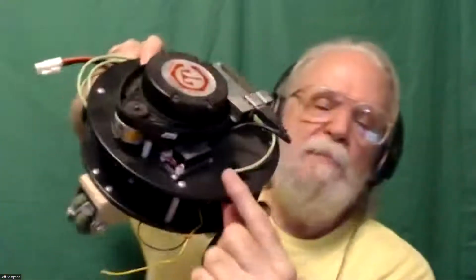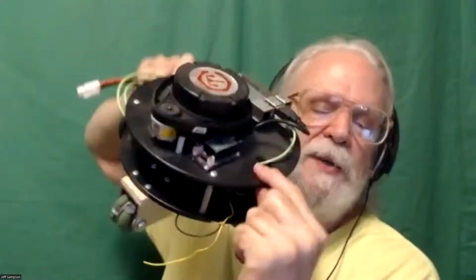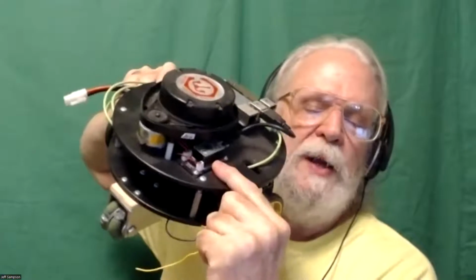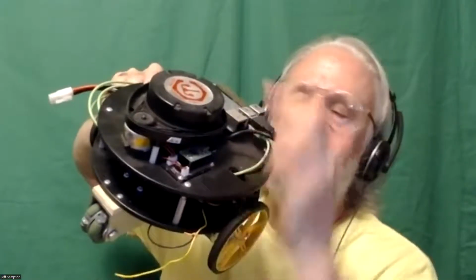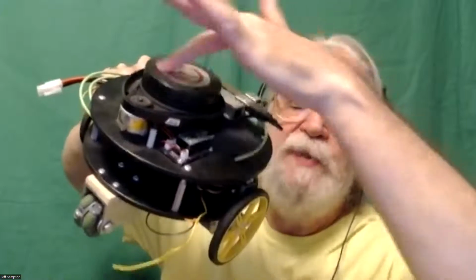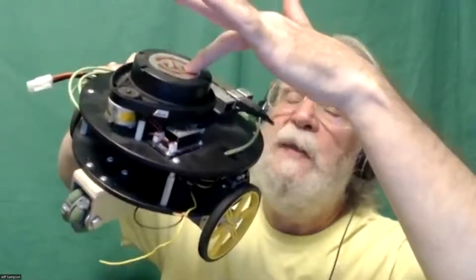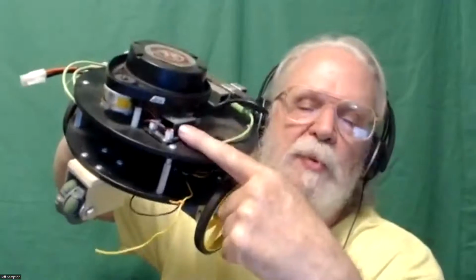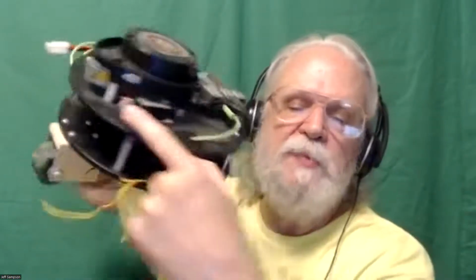But as long as I use, say, a LiDAR, this I think is the XV11, the original vacuum cleaner LiDAR that they came out with. So that one, in this case, is plugged directly into a little board that a guy in the Dallas robot group made, right here. It's got a Teensy 2.0 on it, and it connects to the motor and controls the speed of this. It's just got a MOSFET and a PWM to control the speed, and then it's got a serial line that comes back probably right here, and then it's got a USB connector on it.